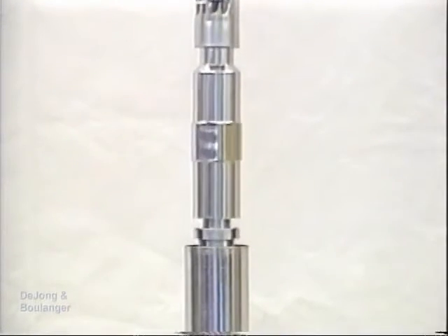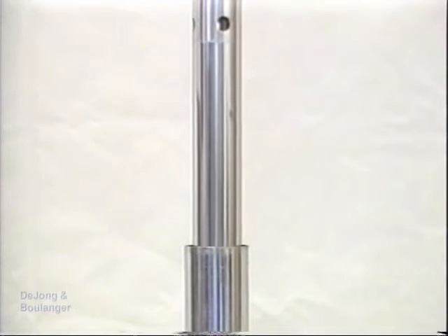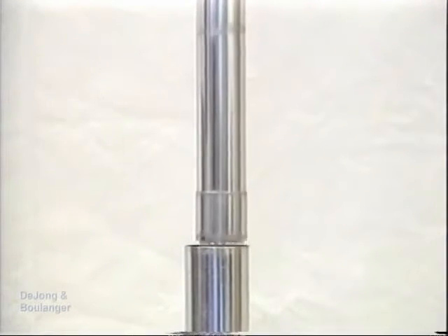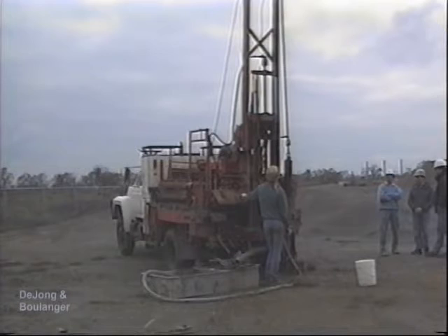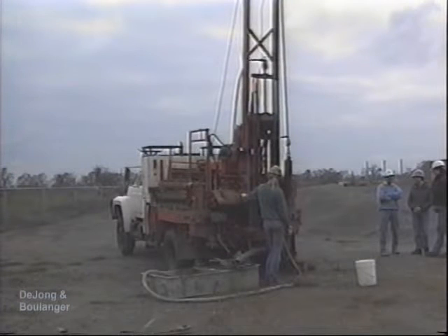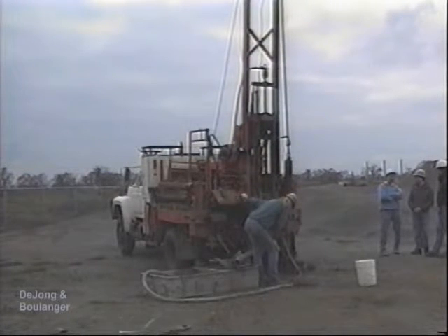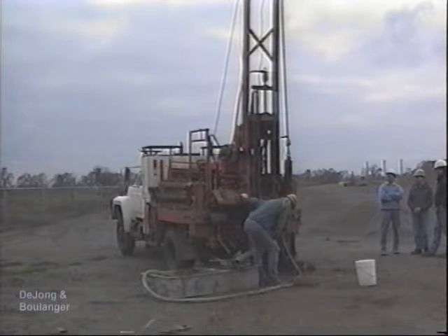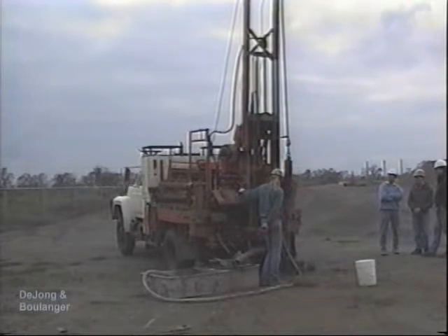Wireline retrieval systems expedite coring by removing only the full inner barrel from the hole, thus retrieving the sample while leaving the outer barrel and drill rods down the hole. The type of coring equipment and operating procedures can greatly affect the quality of the retrieved rock cores. Rock cores can be heavily fractured and damaged by the coring process. Failure to distinguish between natural and drilling-induced fractures on the drilling logs can lead to a completely erroneous interpretation of a rock mass's characteristics. Alteration to the drilling equipment and procedures can significantly improve the core quality and percent recovery in many situations, and these changes should be recorded on the drilling logs.